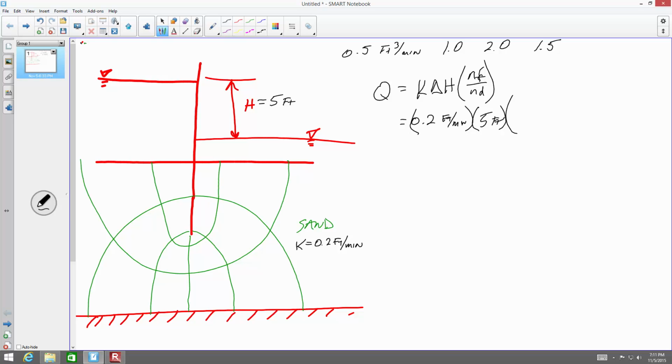Number of flow channels. How many distinct flow channels are flowing water underneath that structure? I get right in the narrowest section and write down what I count.